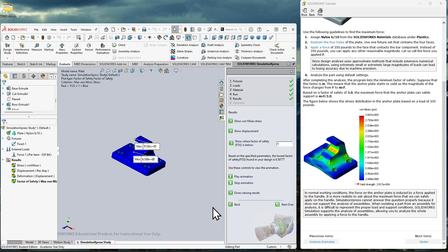The only thing maybe that's worth noting is that this is all theoretical stuff, so it's assuming that the material is perfect. There's never a perfect material, with the exception of maybe a turbine blade, since we actually nucleate those from a single crystal when we're making some of the gas turbine blades nowadays. But most materials don't have perfect crystal lattice structures, or not even crystal, just perfect structures holding them together, because plastics are polymers and those could be like chains. So they're not uniform by any means. So this is assuming that they're uniform throughout, which is a perfect calculation.